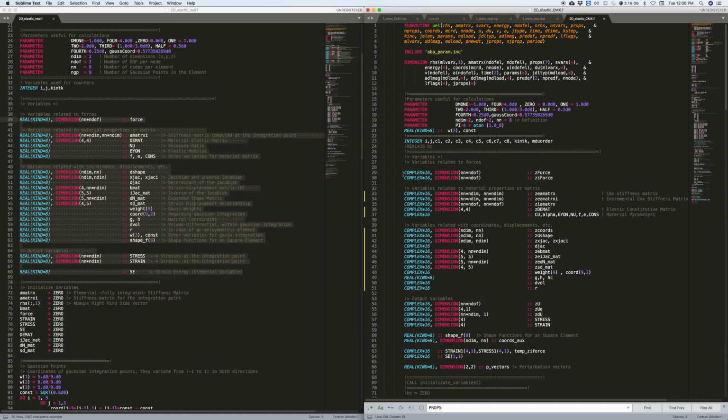The difference is that if I apply a perturbation to, for example, the elastic modulus, my Hooke's matrix, my material matrix, is going to be complexified, right? Because that material depends on the elastic modulus, right? So here the complex variables are those that, if I apply either a material perturbation or a load perturbation or a shape sensitivity perturbation, are going to be complexified, okay?